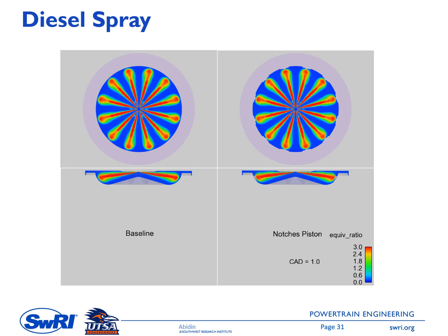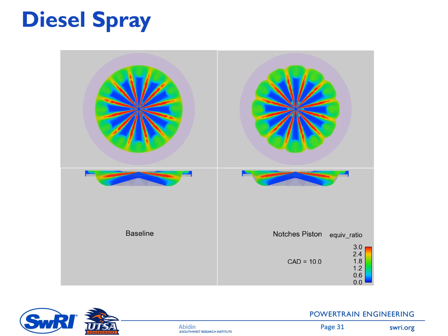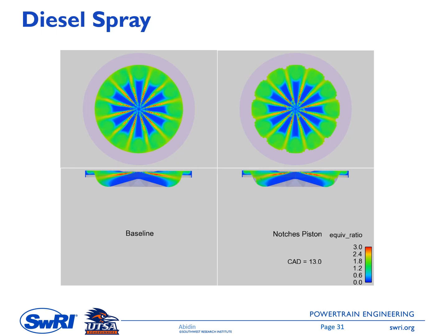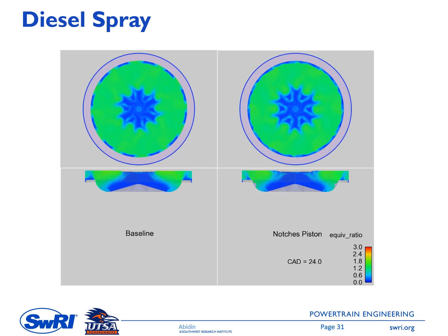The spray hits the piston and is deflected up and down, going into this pocket region, and some of the fuel will go to the center of the region. Okay, so we will learn this diesel spray in more detail in chapter 10.